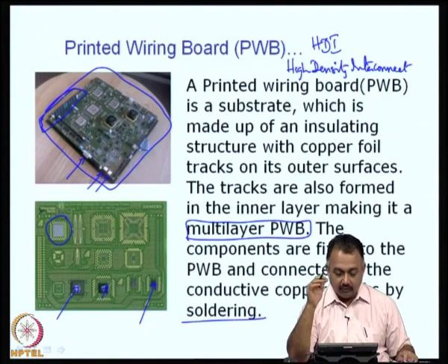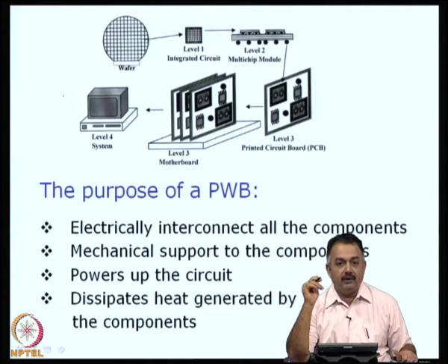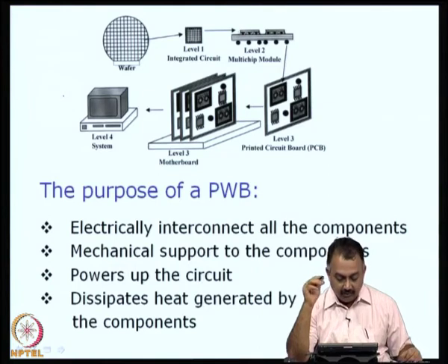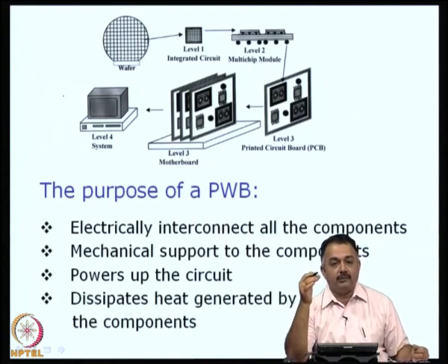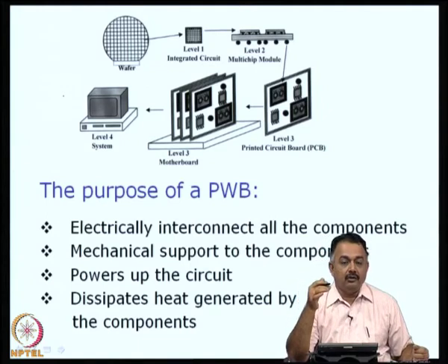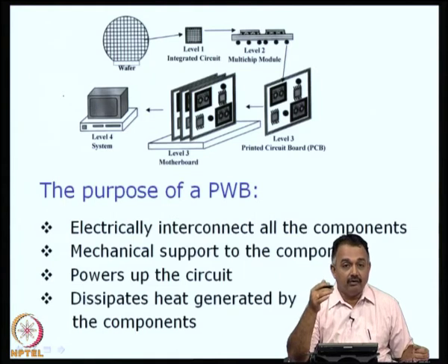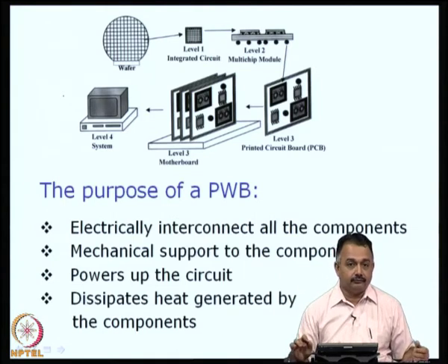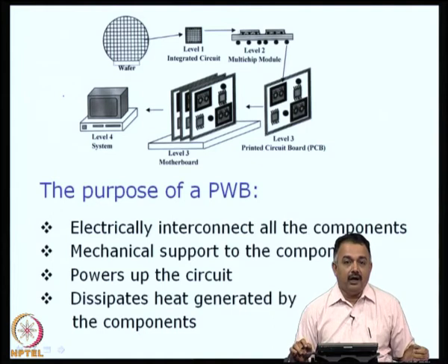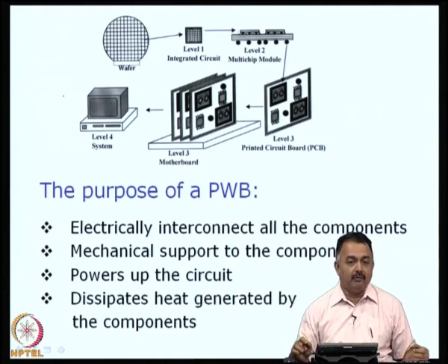I hope you can go through it once again. So, the purpose of a printed wiring board will be to electrically interconnect all the components, provide mechanical support to the components, power up the circuit, and it also dissipates heat generated by the components. So, naturally you can expect the dielectric material that is used for the printed wiring board to be somewhat thermally conductive, remove heat to the ambient, to the atmosphere, right. And you can also improve the thermal performance by adding heat sinks.